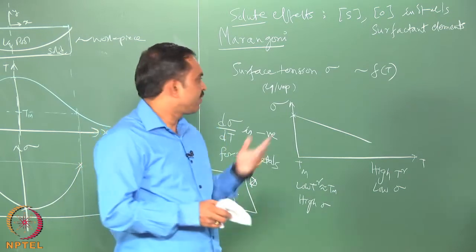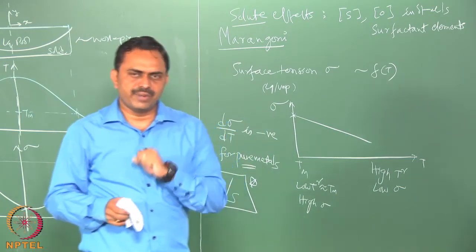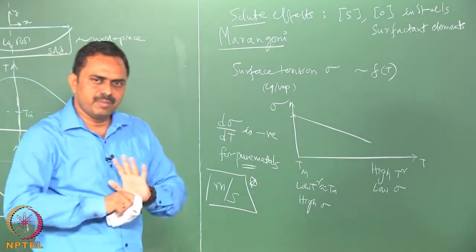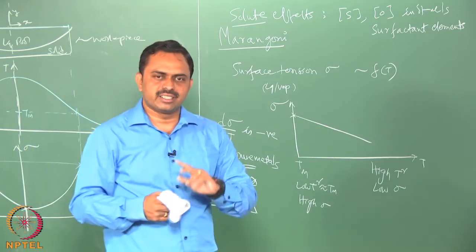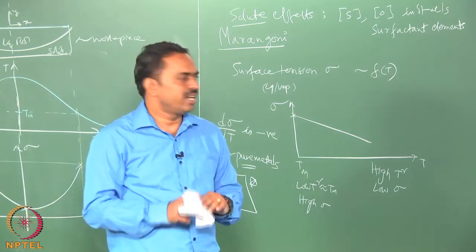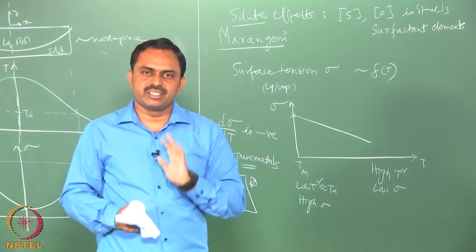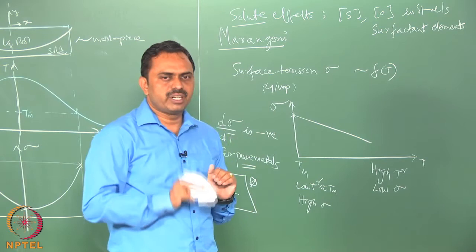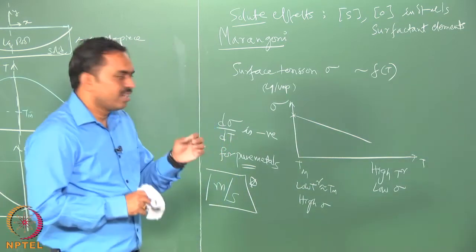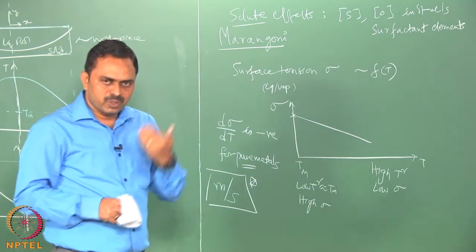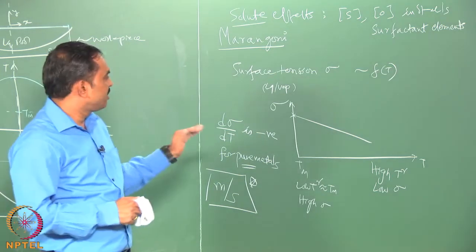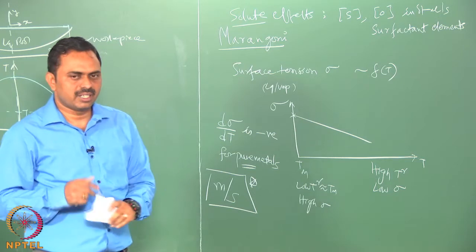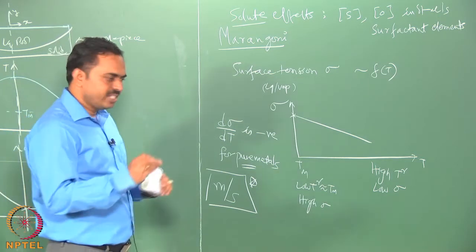Some soluble elements, like for example nickel in liquid iron, do not behave like that. They will be in the substitutional positions wherever iron is there, and they will not segregate selectively to one boundary. However, let us say boron, sulfur, oxygen, etc., they will tend to migrate to the boundary and segregate there, changing the composition locally, so that the surface tension is lowered. Okay. So, such elements, if present, are going to change the surface tension behavior of that particular liquid metal. And how does it change, in what way?